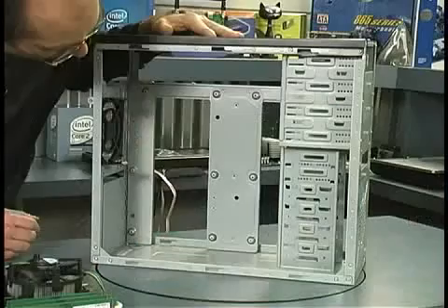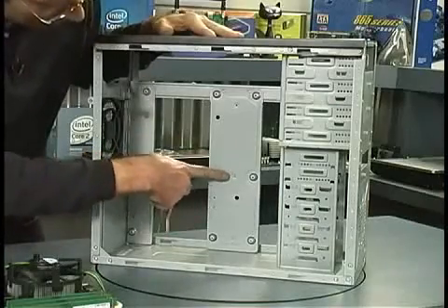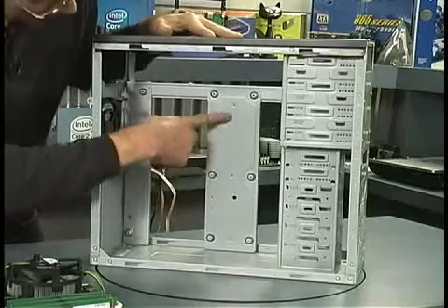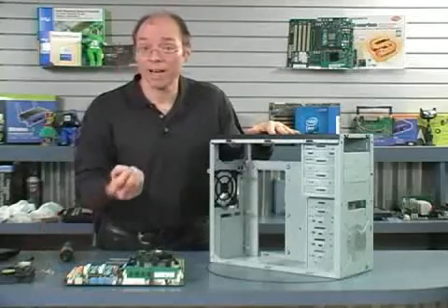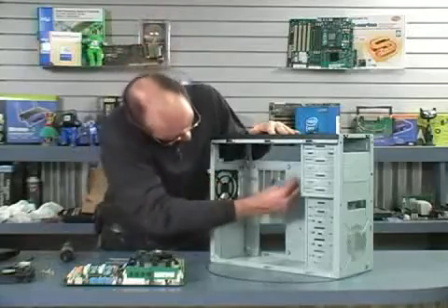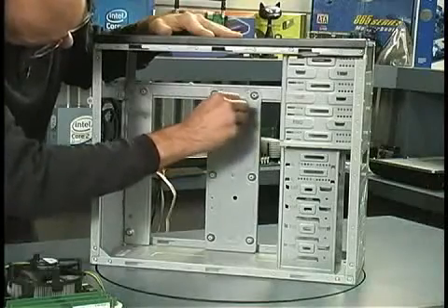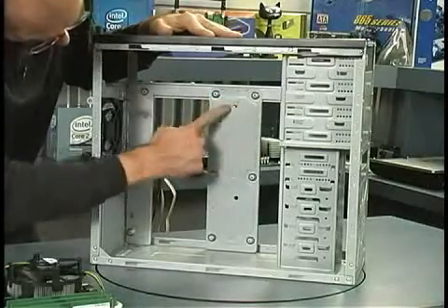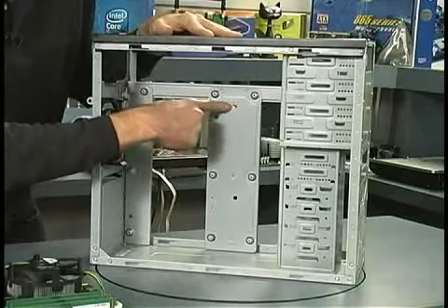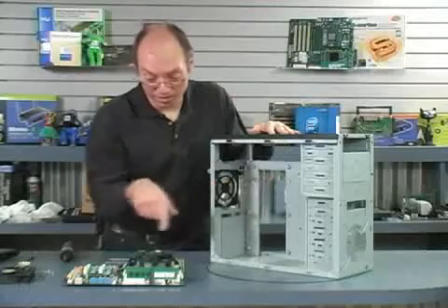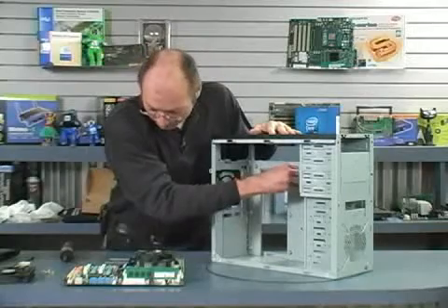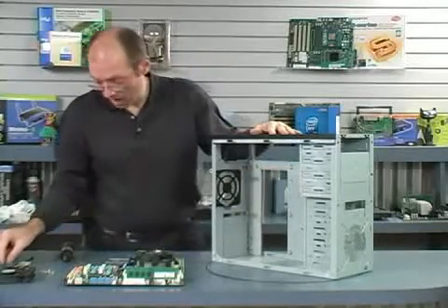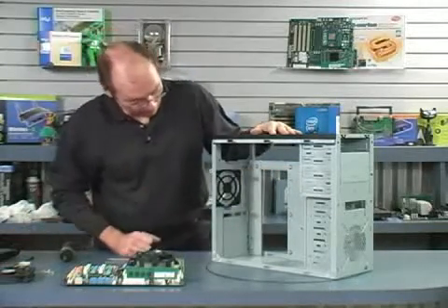Now in some cases you'll find motherboards that require screws in different positions. You'll notice some extra drilled holes here, and usually the little bag of screws that come with the motherboard will provide extra standoffs like this one that you can screw in if you need the support in those areas. Now make sure that they match the holes in the motherboard. So in this case, the existing 9 holes are exactly what's correct for this board.